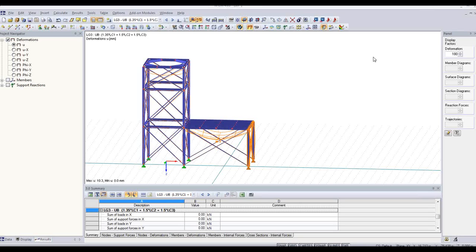Thank you, Chelsea. We've seen the creation of the loads, and one special feature actually is that you can place a concentrated load at any part of the member without creating a node there. That is not common for all software. Or also this area load converter that converts area loads automatically into member loads, and is also updated after structure changes.